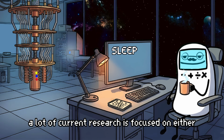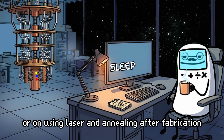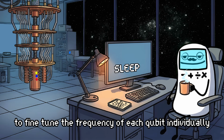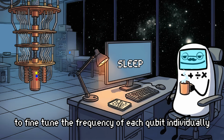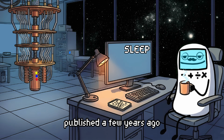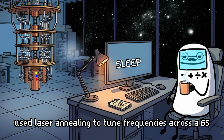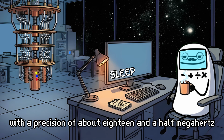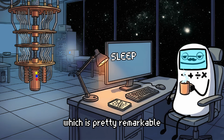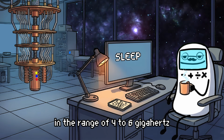A lot of current research is focused on either better fabrication methods or on using laser annealing after fabrication to fine-tune the frequency of each qubit individually. There was actually a really interesting paper published a few years ago where researchers used laser annealing to tune frequencies across a 65-qubit processor with a precision of about 18.5 megahertz, which is pretty remarkable given that the qubits have frequencies in the range of 4 to 6 gigahertz.